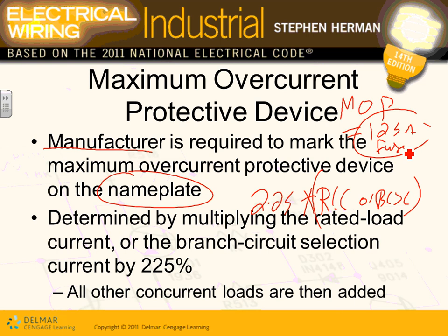Any comments, gentlemen? Any questions? I want you guys to understand these fully. These are very, very important. Right here: maximum overcurrent device, minimum circuit ampacity, right on the nameplate. If you don't have them, you multiply by 2.25, or the ones that you did with me, the code says 1.75. If it doesn't start, you go to 2.25. The manufacturer used the 2.25. They size them, they put them on the nameplate, done. You don't have to do anything.